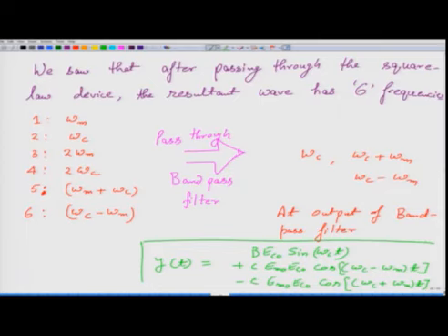Now, typically the power of this amplitude modulated wave that we have just generated, after passing the modulating wave and the carrier wave through an adder first and then to a square law device, the overall power of the wave that has been produced after the band pass filter is very small. So, generally after passing the waves through a band pass filter, we use a power amplifier also. It is to increase the power of the amplitude modulated wave so that it can be now transmitted, and the requirement of any repeater or any amplifier is reduced.